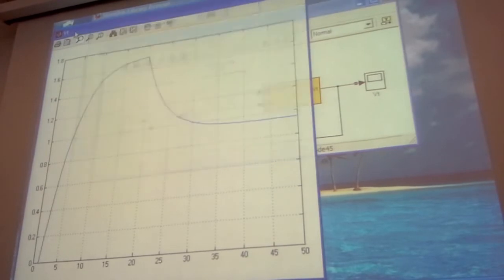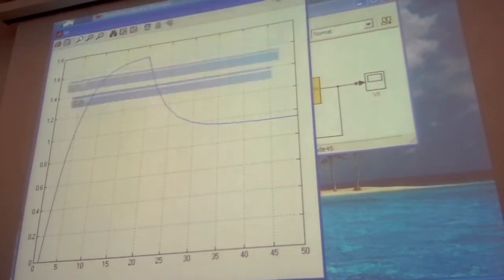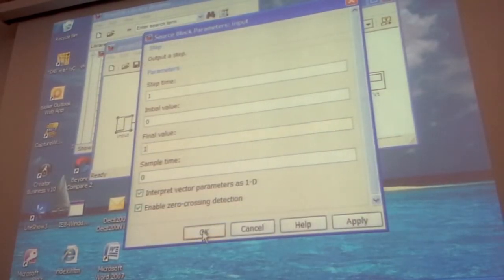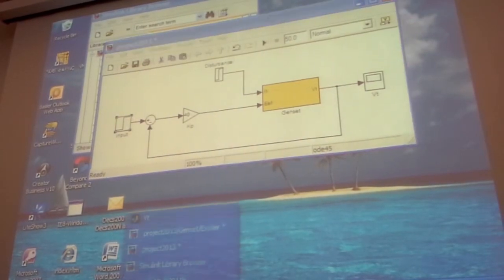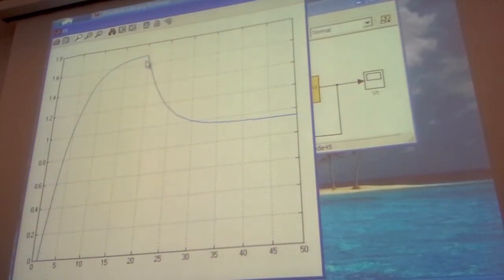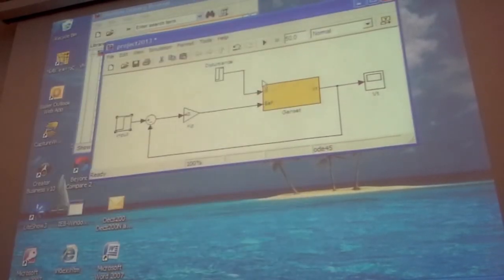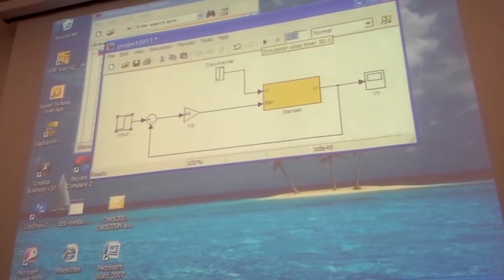So now you can learn here, you can see that. Before it was slow like this, actually slow response like this, right? This is the step response because there is no disturbance. Now look at here. Actually I have to change the step input to 1.02. So now run this guy. How long does it take before? It was about 20, the steady state almost more than 20 seconds. That means now if you do here, actually it's too much, so I'm going to have 5.